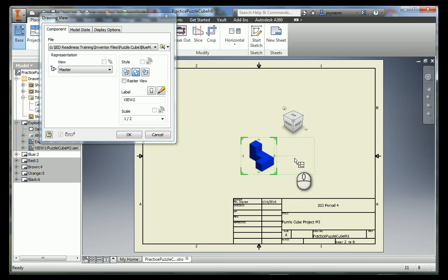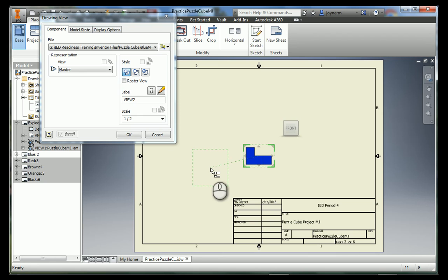So what I'm thinking is we don't use this view. We have to use the front, the top, the right, the left, one of those views in order to pick which one has the most dimensions that we can use. I like the front piece for us here. Okay, so I'm going to click in the bottom left hand portion here. We're not going to click all the way down here because we want to be above the title bar. If we click up here, that places our first.